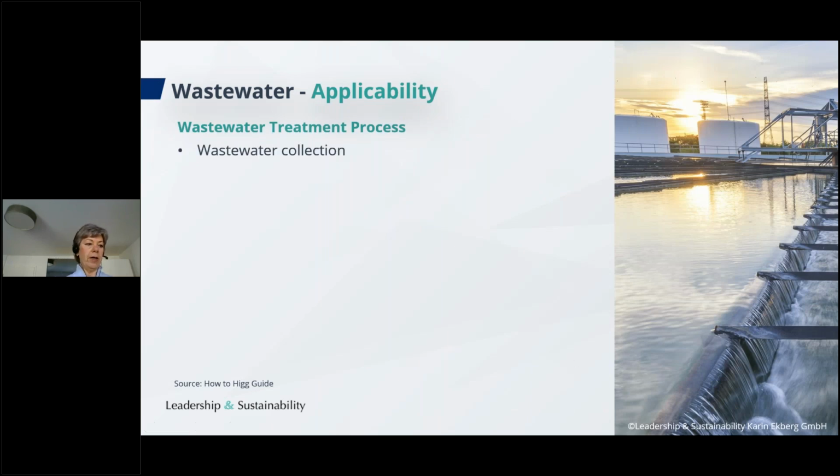First of all, you have the wastewater. It's collected via drainage pipes and directed to a central point. The pipes or tracks should be leak-proof, and the people offering exhaust services should use PPE. And then we have the screening. This process involves the removal of large objects that could damage the equipment. These items must be disposed of correctly. So these might be large meshes, where any debris, any larger objects can be removed.